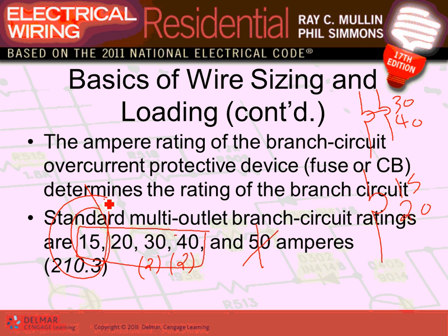So the circuits that I circuit for you guys are 15 amps. Does that make sense? 15 amps. Unless the code tells you 20, it's what? 15. That's the default in dwellings. Did you guys hear me? So important. If you understand it now, you're done with the whole project.